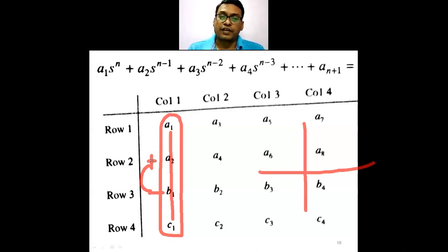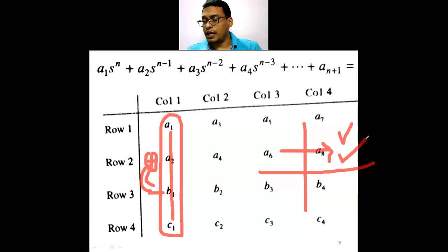That means whenever the coefficients of column 1 change sign, your system changes from stable to unstable, and as many times as this sign change is observed, that many positive roots you will have.